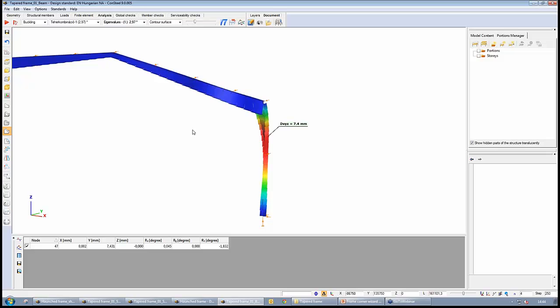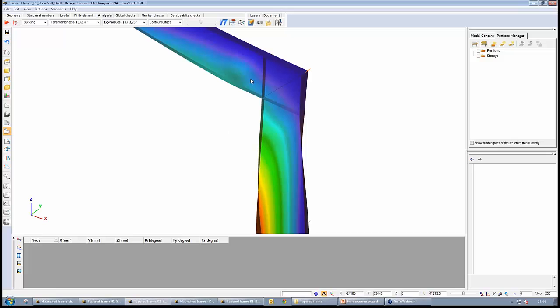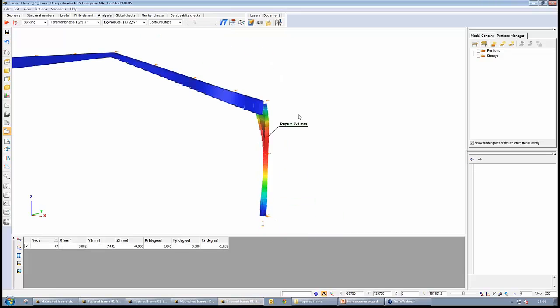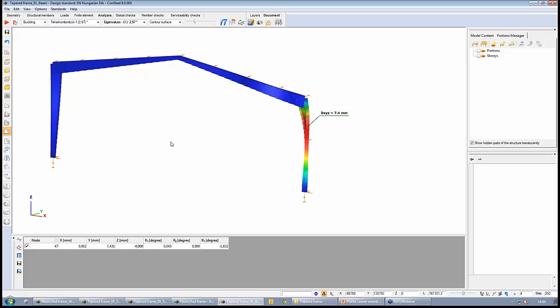Usually for a hinged frame it is enough to use a horizontal stiffener on the column, but for larger cross sections like here and for slender webs, it is very usual that additional stiffeners are used in order to avoid the local buckling effect, like here the shear stiffener, and this is the case where the frame corner wizard gives quite good results. So this is for stability calculation.